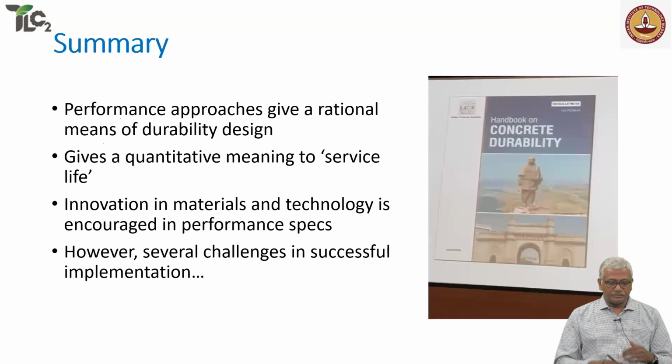Right. So to summarize, of course, the performance approach gives a rational means of concrete design. Without relying just on prescriptions, we go a little bit beyond, understand the mechanisms that can actually affect concrete deterioration and actually design the structure for that. We can provide a quantitative meaning now to service life. Earlier, qualitatively, we were saying, okay, yeah, this will last for 50 years, but now we can quantitatively say, if you design it with this strategy, the structure will last for 50 years.